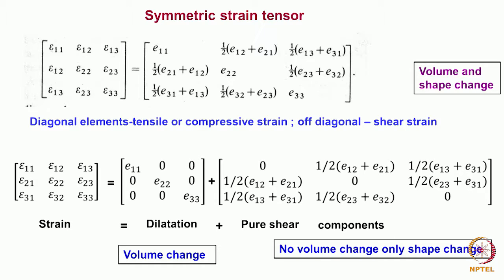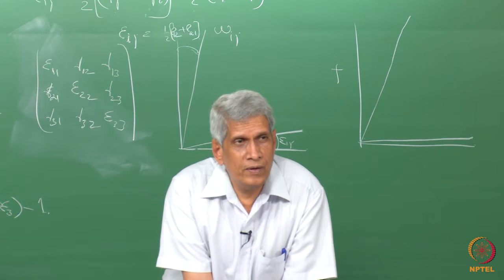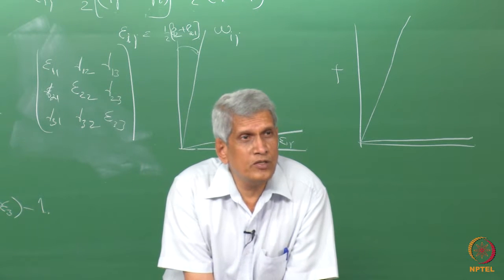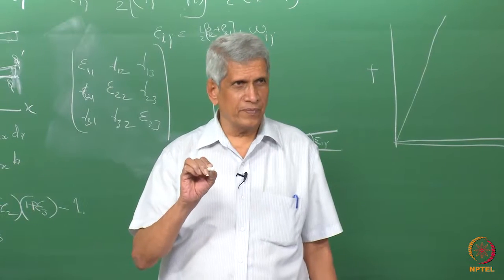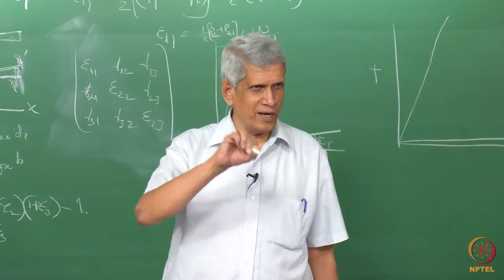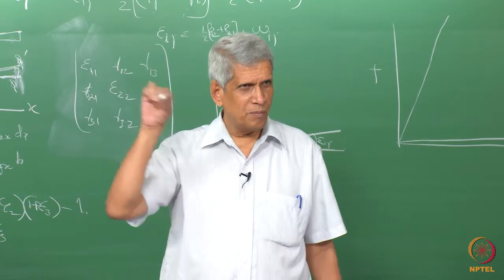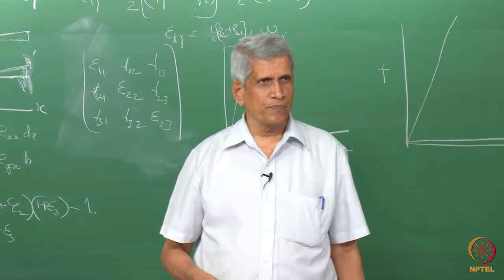So the rotation matrix also, the rotation component that we see, even that is dependent on the amount of shear that we are applying, the amount of engineering shear we are applying. So in the sample at different points you have different amounts of engineering shear applied, let's say in some deformation process. So the local rotation will vary. That is what happens when you deform a polycrystalline material. When you take a polycrystalline material and deform, the interior of the grain undergoes just pure strain, whereas close to a grain boundary, it undergoes rotation. The rotation in the interior, the center of the grain, will be almost zero, but the maximum rotation will be near the boundary. So it's a varying unit. It's not like a complete rigid body rotation.